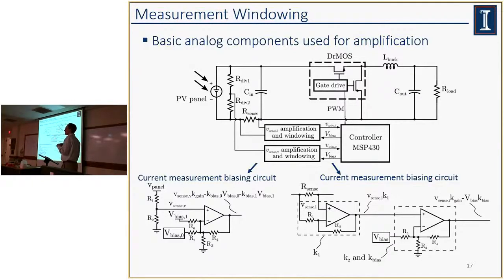We can accept some loss of accuracy in the DC level of that ripple. What we really need is high accuracy in the ripple measurement. So basically what I'm saying is that we do lose some absolute DC accuracy in the measurement because of nonlinearities and non-idealities in this circuit. Also, the circuit obviously changed between converters and that type of thing. But in exchange for giving up a little bit of DC accuracy, we're able to achieve high precision measurements of the ripple signal.